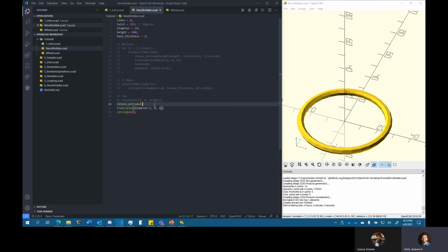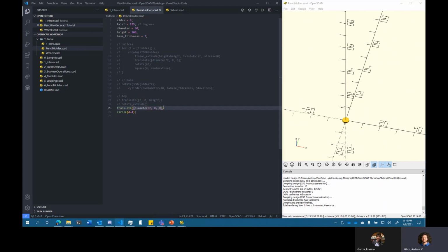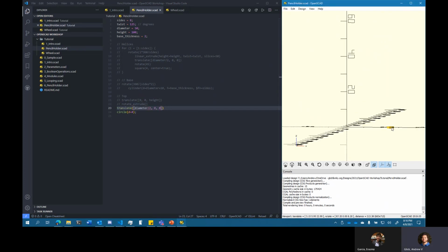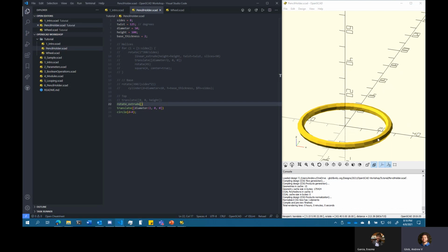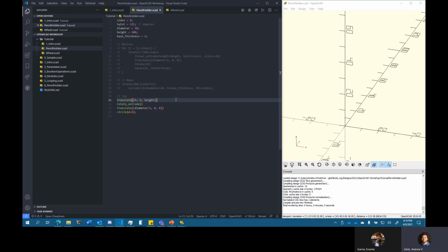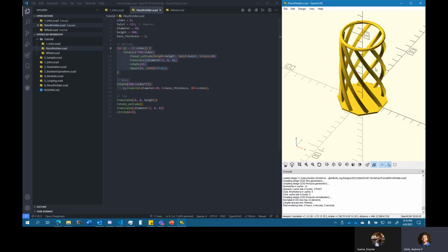And even though the circle, when it's shown here, looks like a 3-dimensional object, that's just OpenSCAD putting a height to it, but it's not really. It doesn't really have any height. It's a 2-dimensional object, so we can just rotate it, and it knows that the z facing up should be then dragged across the z-axis. So you don't have to rotate it to be in line, or parallel, with the rotation. It knows that. Then if we add this translate, that puts it up there, and then we can uncomment all this, and then we get our pencil holder.